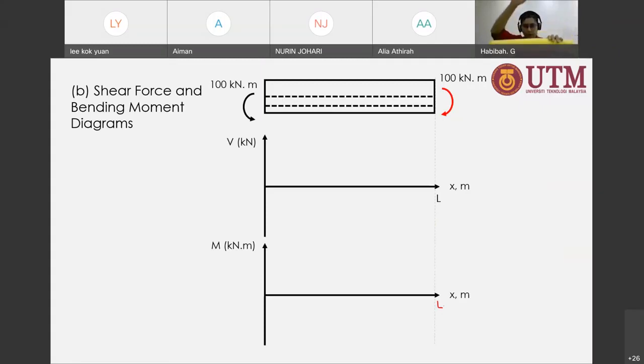Okay, so when we have distributed load or concentrated load, external, pointing downward, there will be a shear force going upward. Or if we have a support, and let's say we have a support reaction here that's going upward, obviously the internal shear force is going to be generated to prevent that.